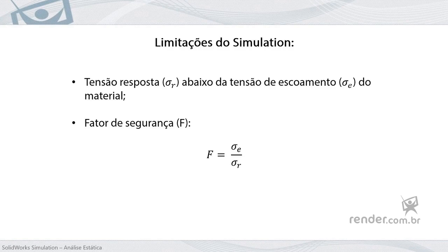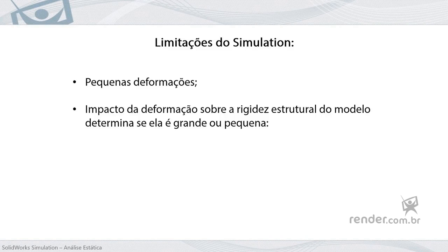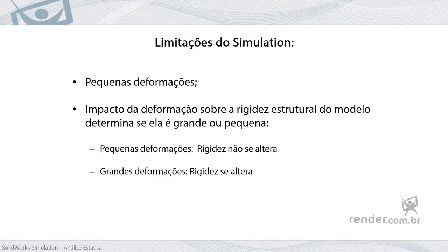Another limitation of the Simulation add-in is its application only to cases where small deformations occur. It is not the magnitude of the deformation that determines whether it is large or small, but whether it affects structural rigidity significantly. The analysis of small deformations assumes that the structural stiffness remains the same throughout the deformation process. In large deformation processes, however, structural stiffness changes during deformation.